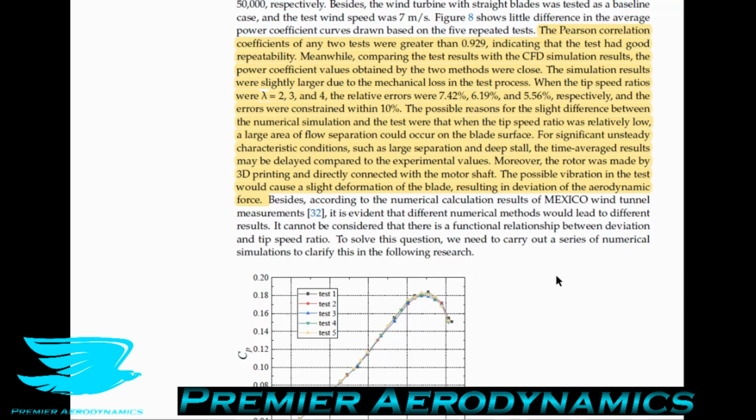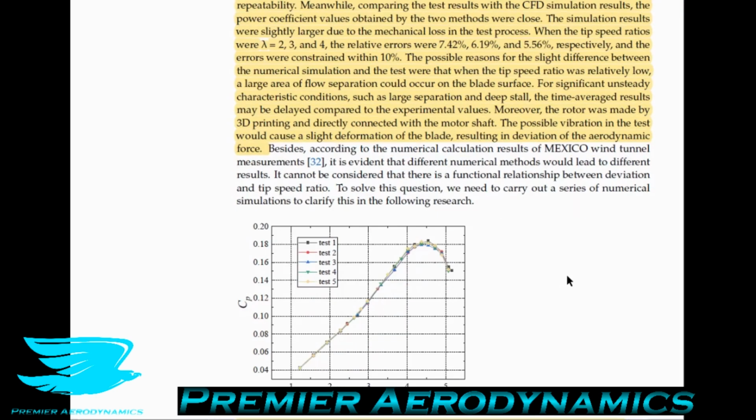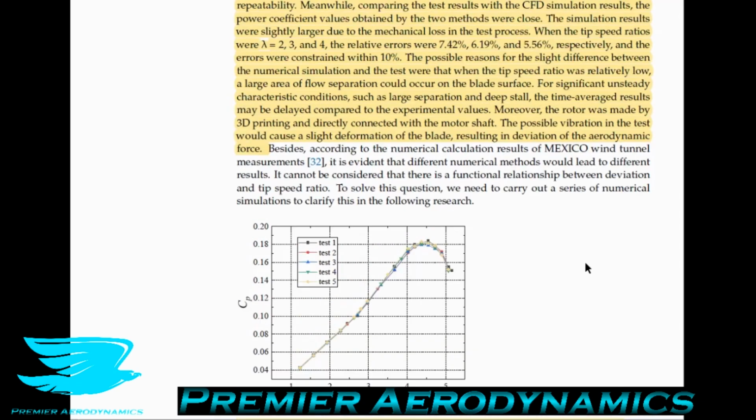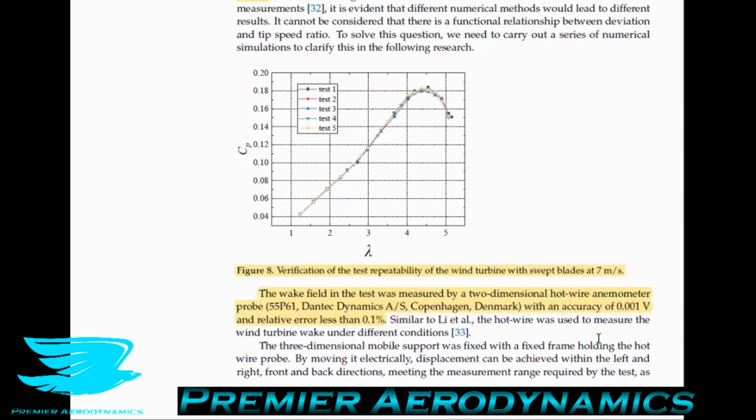So what that means is if you have, let's say, 1 second, and you have the blades at a certain position, well, at time 2 seconds, the blade's going to move differently, and the wake from one of the blades is going to impact the other blade coming behind it. But if you don't have the blades moving, you might still have that wake impacting the other blade, but not in the same way because the blade is at a different angle now to what it would have been. So that's one major limitation of the way that you simulate the rotation of the blades. There are ways around that. There are better CFD simulation methods, but they are far more expensive. So that is another reason why the CFD probably didn't align with the experimental results as much as it could have. So let's move on now.